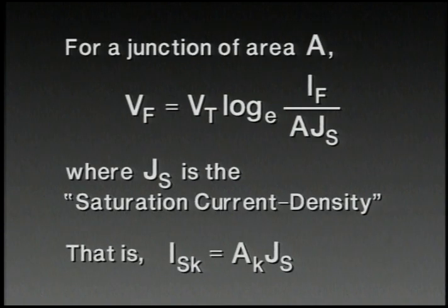That's very readily done. The I sub s for a junction of area A is simply proportional to the area of that junction. Perhaps we should say, as a practical matter, it's not exactly proportional to area. There are subtleties, but certainly if those junctions are made, for example, as integer units, say of 2 junctions of identical size or 8 or whatever, then that would be true.